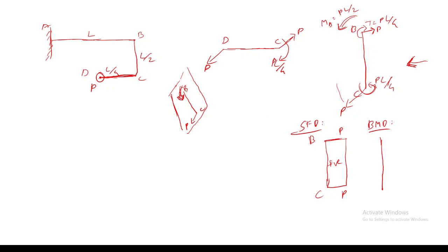Negative. Can you actually say which surface gets contracted? For example, this is the member, right? So based on this loading, which surface actually gets contracted? The front surface or the right surface or the back surface? So when we view from the right, the left side is getting contracted. Yes. So when you are viewing from the front, the front surface gets contracted. So it will be negative, right?